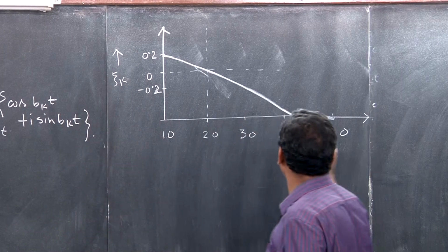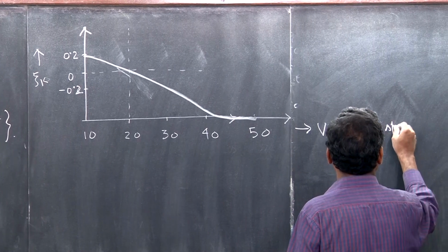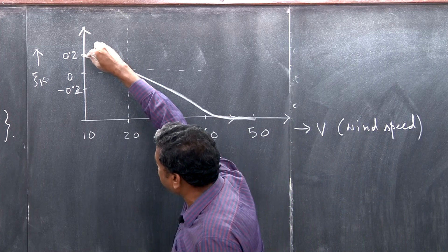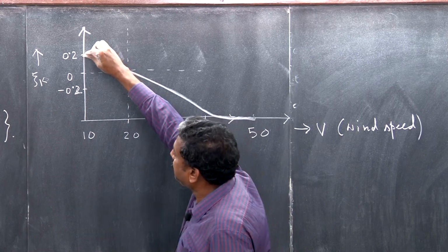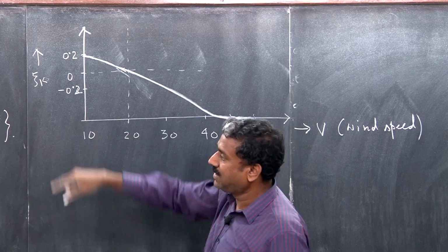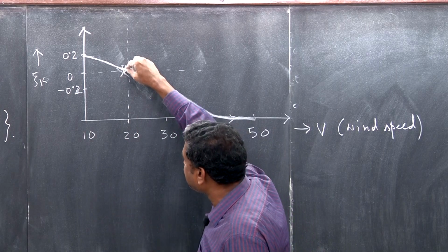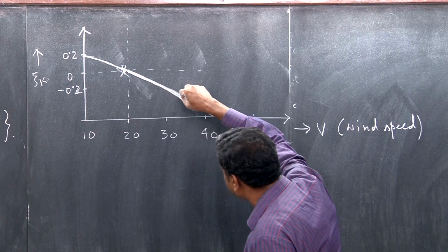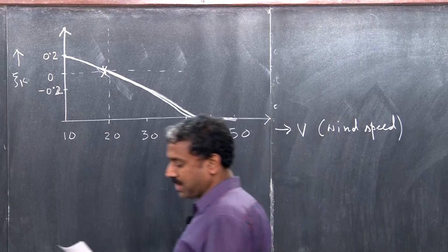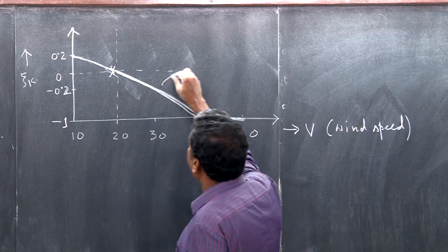For different values, this is nothing but wind speed, v, wind speed, for increasing wind speed. You see that? So, from positive damping, and this is the damping ratio. The positive damping is coming and crossing zero damping. What is the value? Zero damping at 18 point something, that is what I have for the Tacoma bridge, right? After that it comes to this, and then beyond 40 it will once again go around 1. This is minus 1, that means 100% damping. You see how damping is changing.